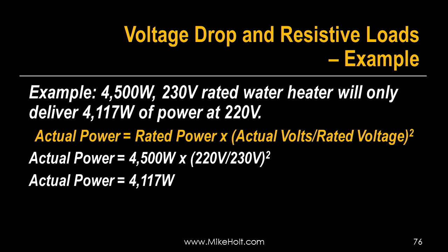I like that as an example. If I'm using 240, 10 kW at 240 is 7.5 kW at 208. Okay, take 208 and 240. What's that percentage? Just 208 divided by 240. That was 87%. And then what's the square of 87%? 75.11. 75%.